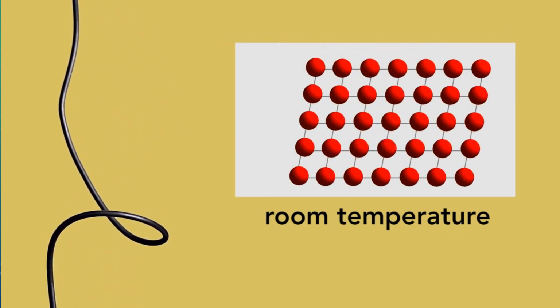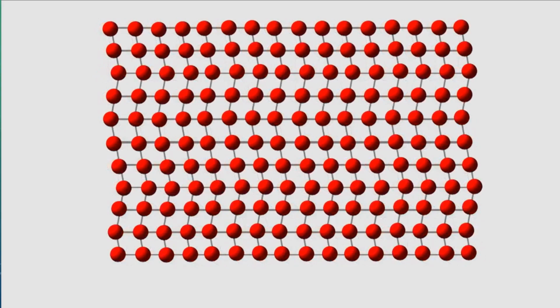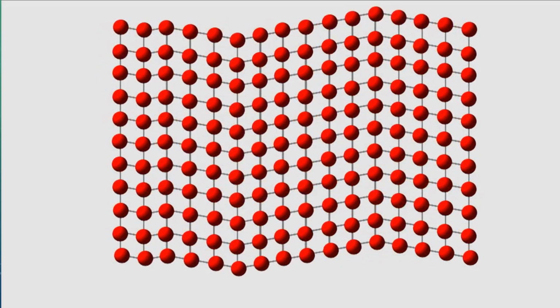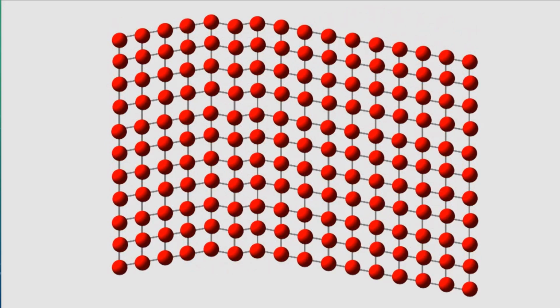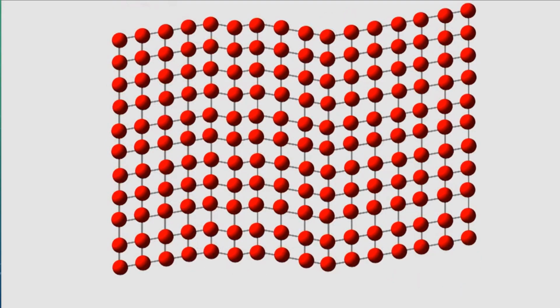Notice that in response, the atoms move and change the ratio of the two types of rhombuses. In this example, they all change to one type. You could imagine that in response to different forces, in a large enough crystal, there would be hundreds of mixtures of these two rhombuses, and many, many more in a three-dimensional structure. But notice this. At all times, the atoms are connected in the same way as in the high-temperature phase.